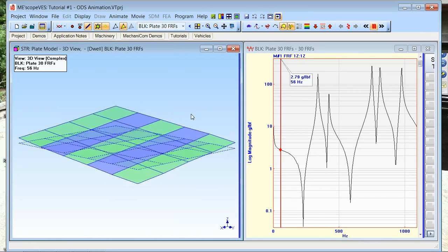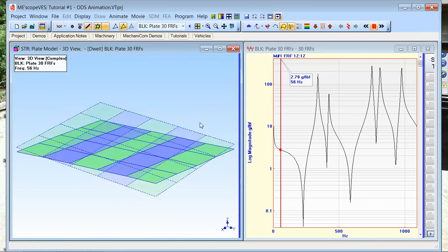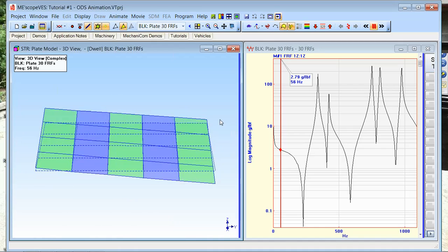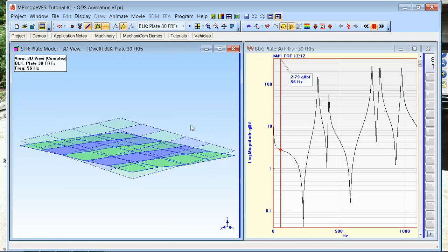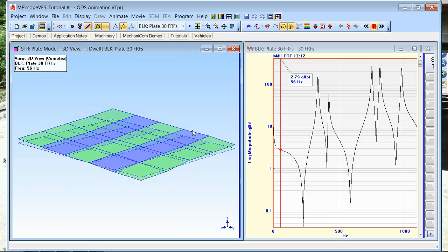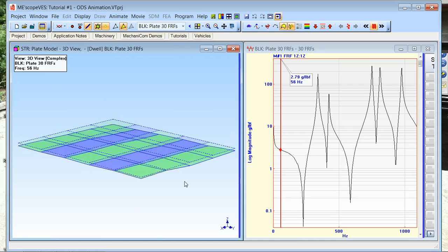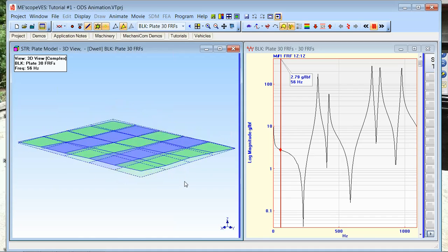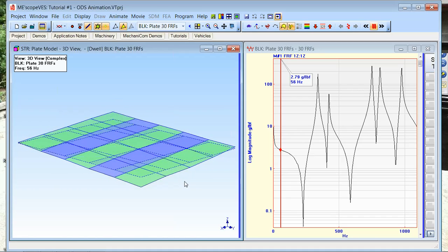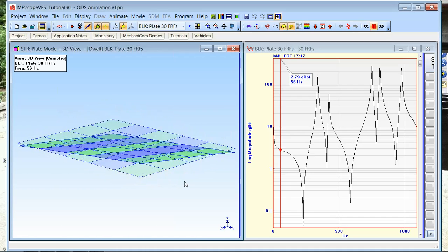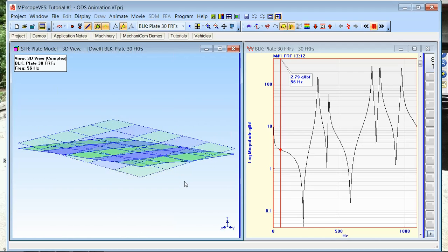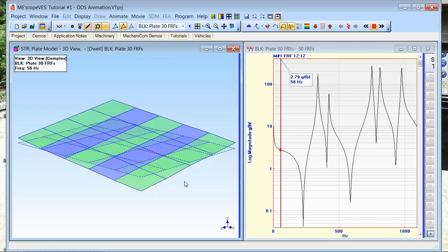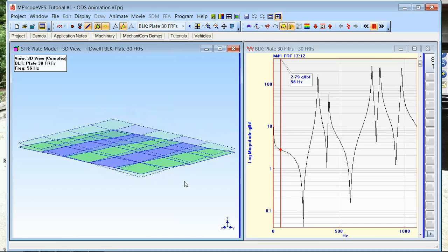But I'll see one in a car body or an airplane fuselage very similar if I test it in a semi-free condition like this. Now, if it was mounted to a wall, or if this was a piping system and I had it rigidly mounted to a wall in certain places, the mode shape would look a little different. But I would still see a very simple waveform which I can recognize and give a name to, called first torsion. Now let's go to this next peak.